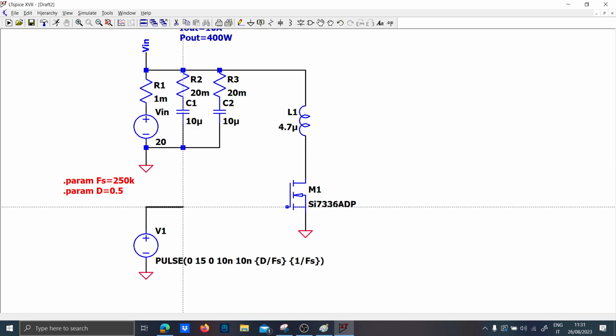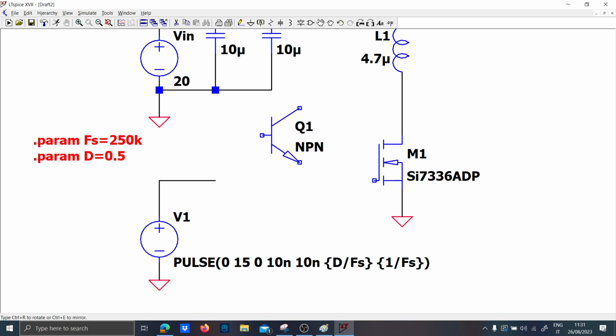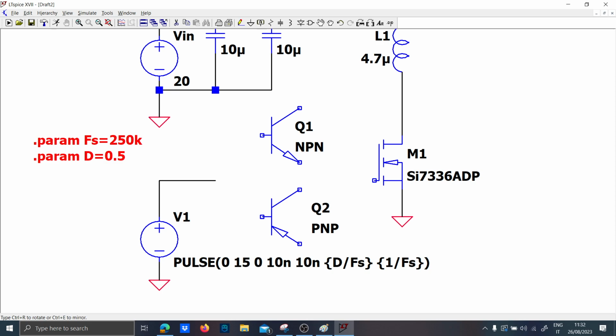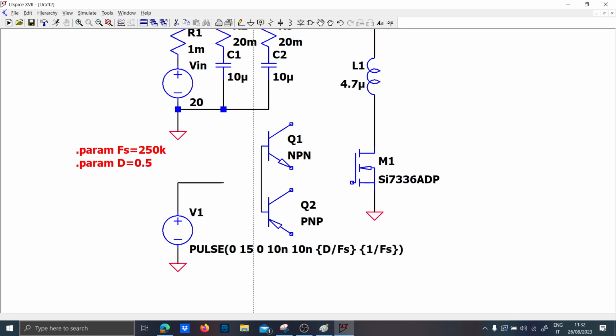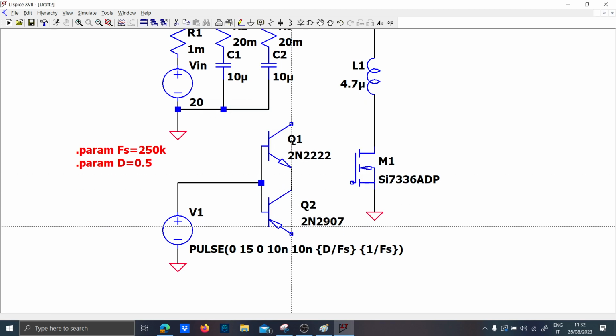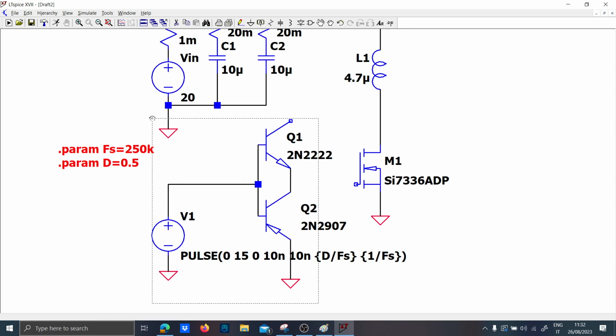Now before going here, you need the emitter follower stage, which is made by NPN and PNP, because this voltage will basically be generated by a microcontroller, and we probably need also a level shifter for that. But let's skip the level shifter and go directly to the push-pull stage, which is used to give current to this guy. It is basically a low side driver.